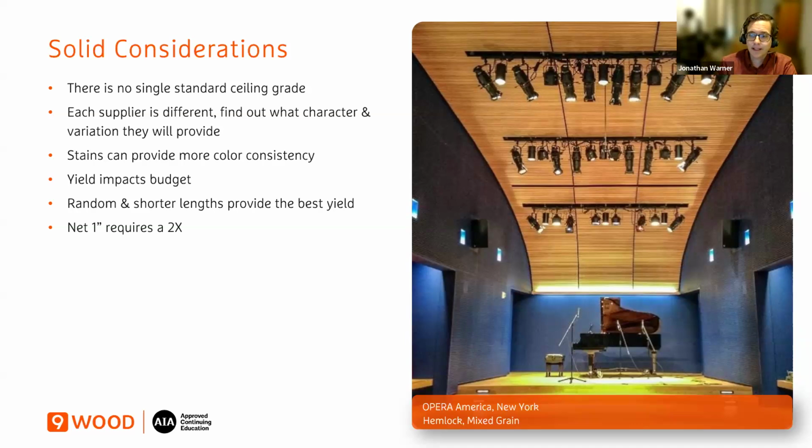The other thing to keep in mind is if you want a net 1 inch, exactly 1 inch, not nominal, like a 5/8 or 3/4, that's going to require a 2x. And so if you go to Home Depot and you see all the 2x material, the manufacturer is going to buy a much bigger size, mill it down, and a lot of that's going to go in the waste. And so it has an additional cost. So make sure if you specify 1 inch, that's exactly what you need.